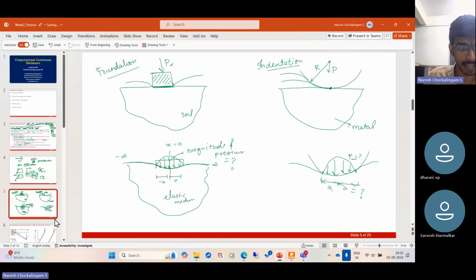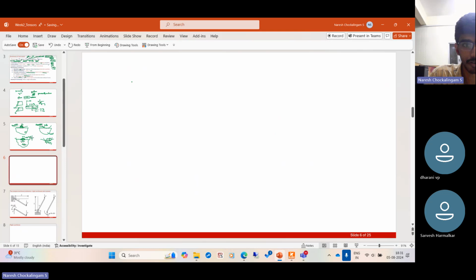The other kind of nonlinearity is force nonlinearity. Suppose you have a cantilever beam, and the force is acting such that it is always perpendicular to the beam. This boundary condition is typically hard to get in reality, but you think of it as some kind of pressure. So pressure acts always normal to the surface. A pressure acts always normal to a surface. So which means after the beam bends, this force is still normal to it. So such a force is called a follower force.